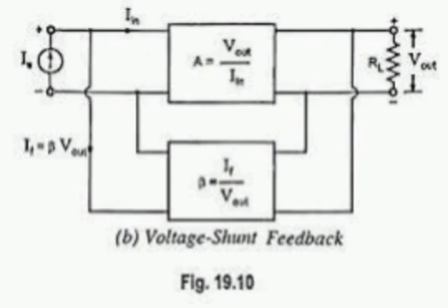Remember, it has highest conversion efficiency among all power amplifiers. Class C output is heavily distorted. It is used in tuned power amplifiers and radio frequency amplifiers. The maximum efficiency of Class C amplifier is 87.5%. Class A power amplifier, conduction angle is 360 degrees, maximum efficiency is 50%, figure of merit is 2.